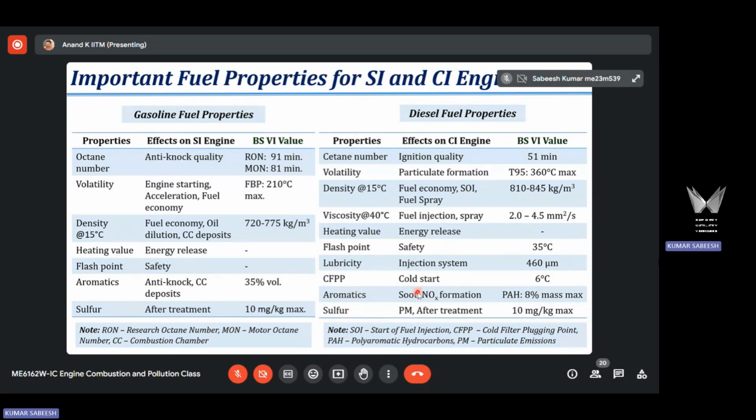High aromatic content is also known to cause higher flame temperature, and higher temperature forms high NOx. One of the primary mechanisms by which NOx, oxides of nitrogen, is formed in the cylinder is high temperature. Aromatics cause higher temperature during combustion, and thereby form NOx. I will provide a more detailed discussion of this mechanism in the second module. But here just take note that any increase in aromatic content in diesel fuel will increase both soot and NOx from a diesel engine.